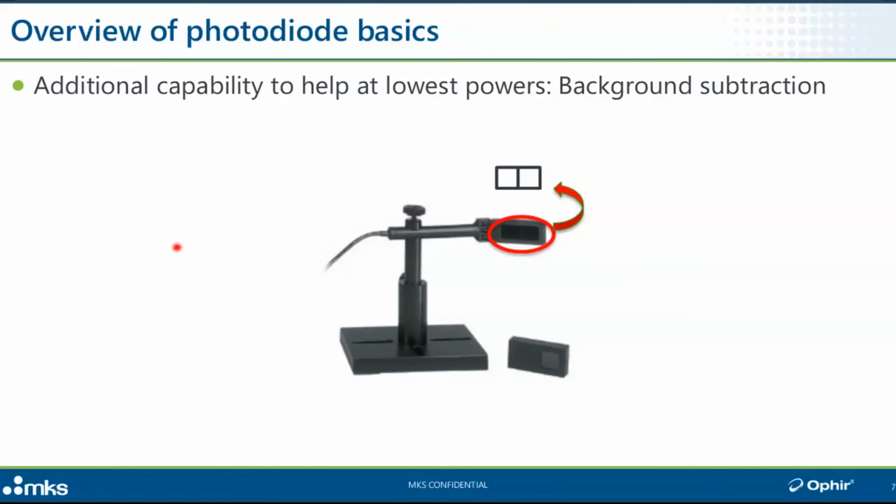So what we do is we have, I don't know if you can see that here, 2 photodiode detector elements connected one next to the other. The concept is that the laser beam that you want to measure is going to be incident only on one of them. The background light, it's a pretty safe assumption that it's reaching both of them equally. And the instrument automatically subtracts one from the other, and that gives actually something like a 98% effective background subtraction. So that's a neat trick that we use in some of our models.